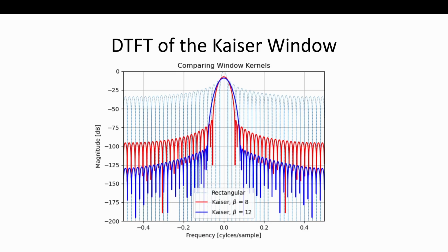You're trading your main lobe width, which is going to be your frequency resolution, how much you can really resolve a frequency, versus how far these side lobes are down, which is your dynamic range. Picture trying to work with two signals, one really strong, one weak next to it. It'll be totally buried by this. It wouldn't even have to be next to it. It could be way out here, two signals, one there and one there. And if we processed it with this rectangular window, the other signal would be completely buried. You picture that?